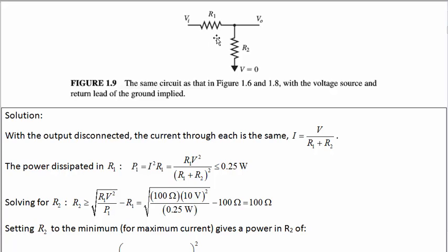It's like if the resistance goes way up, so it stops the current flowing in the circuit. That's probably bad, but it's not usually nearly as bad as failing to close. This is when the resistor burns out and becomes a short circuit, allowing a lot of current to go through, probably breaking other things elsewhere in the circuit. Either way, though, there's a lot of heating up that happens before resistors fail, so this could cause fires and other nasty things. Basically, try not to exceed the power limit in your resistors.